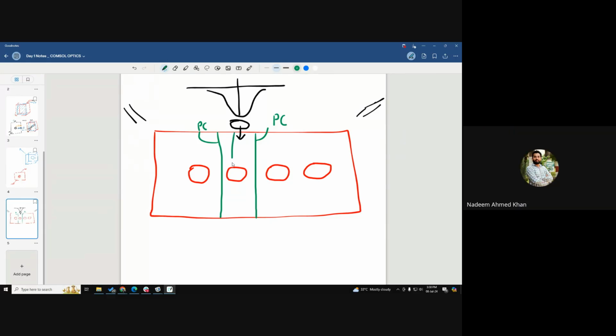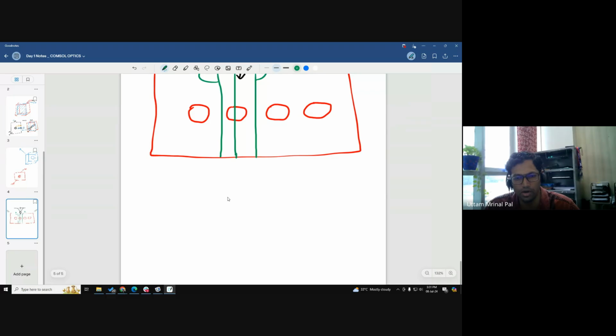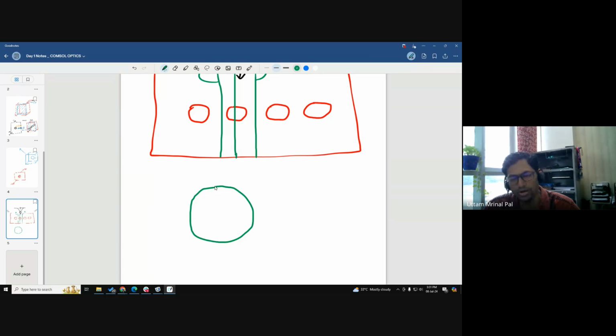Can we even further minimize this geometry by using only a quarter or half of the hole, because in FDTD people do that, they just simulate a quarter of the hole? Yes, you can do that. There are a few examples. If you have seen the nanoscatterer example, in it they model only a quarter of this gold nanoparticle. In that you have to be very smart because you have to play around with boundary conditions, because in COMSOL electromagnetic physics, unfortunately, there are no symmetry boundary conditions.